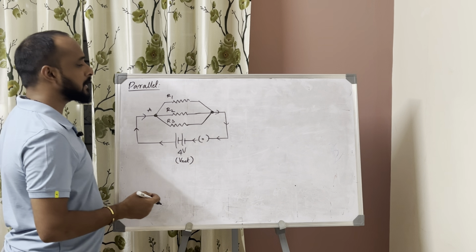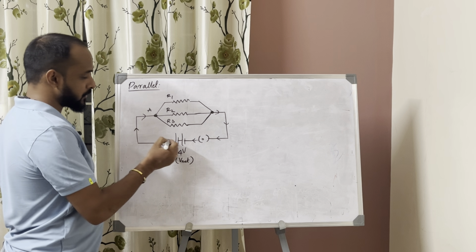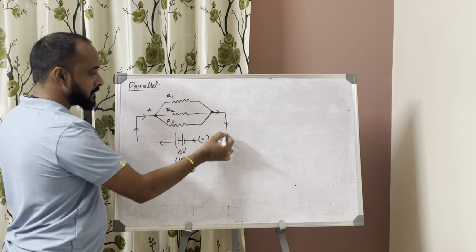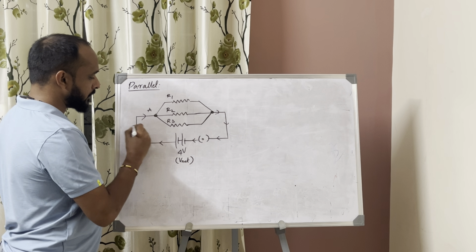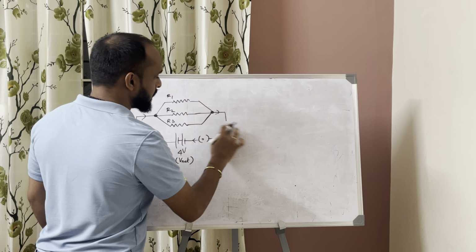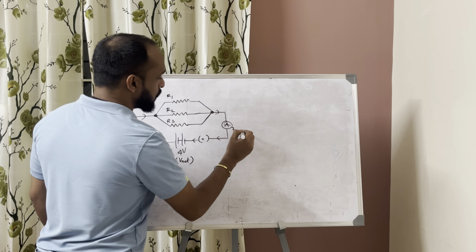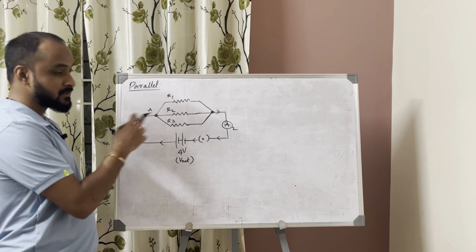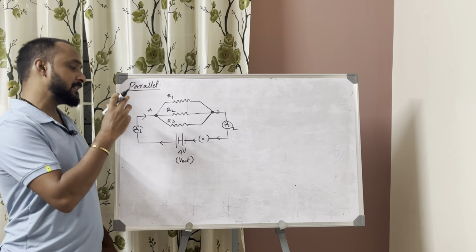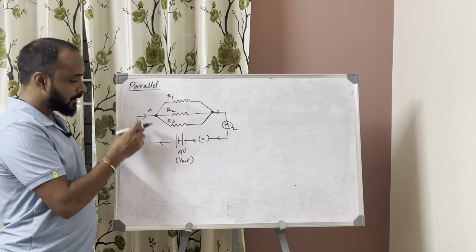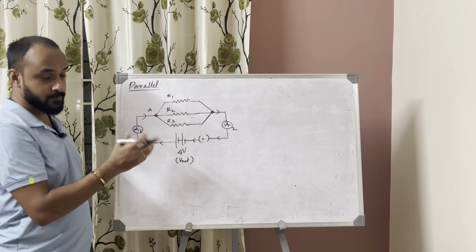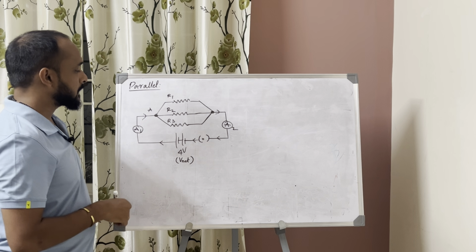So if I were to connect an ammeter, I could connect it anywhere in the main circuit. To measure the main current, I could connect it anywhere in this main circuit. For example, I could connect ammeter 1 here and ammeter 2 here and one more time. What is an ammeter? Something that measures current, and the resistance must be almost equal to 0. We always connect it in series. These two will give you the same values. We'll see it at the end of the class.